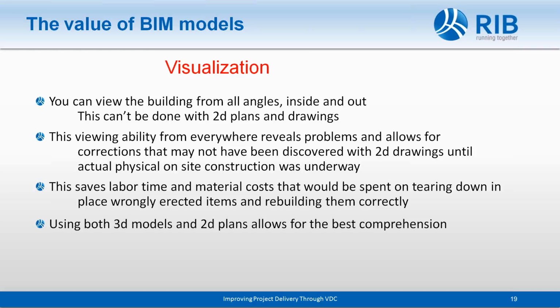It helps you possibly see any problems that may arise in the actual construction process within the model, and so you can take steps to correct things prior to actual physical construction. Okay, and that helps save rework, that is the tearing down of some construction items already installed or placed and building them again. That's again part of all that waste we talked about earlier.